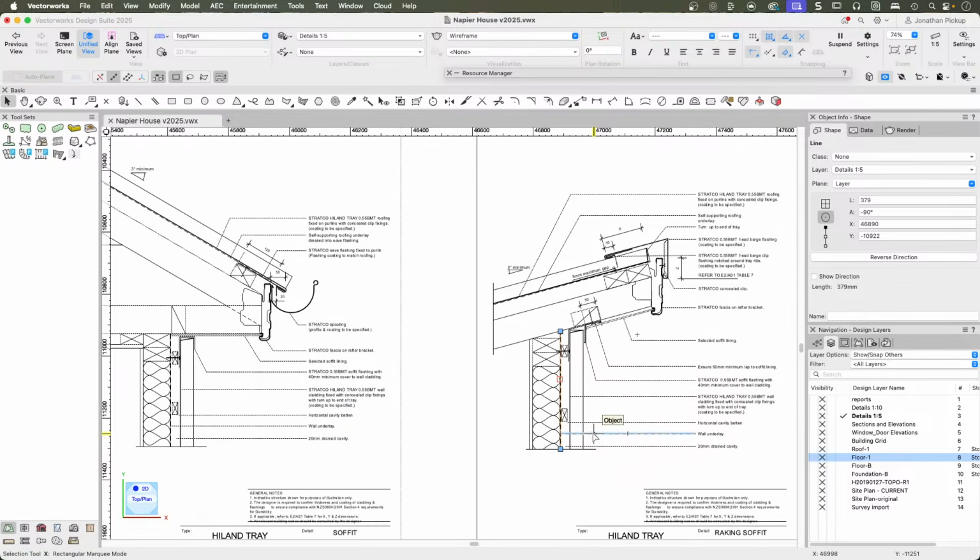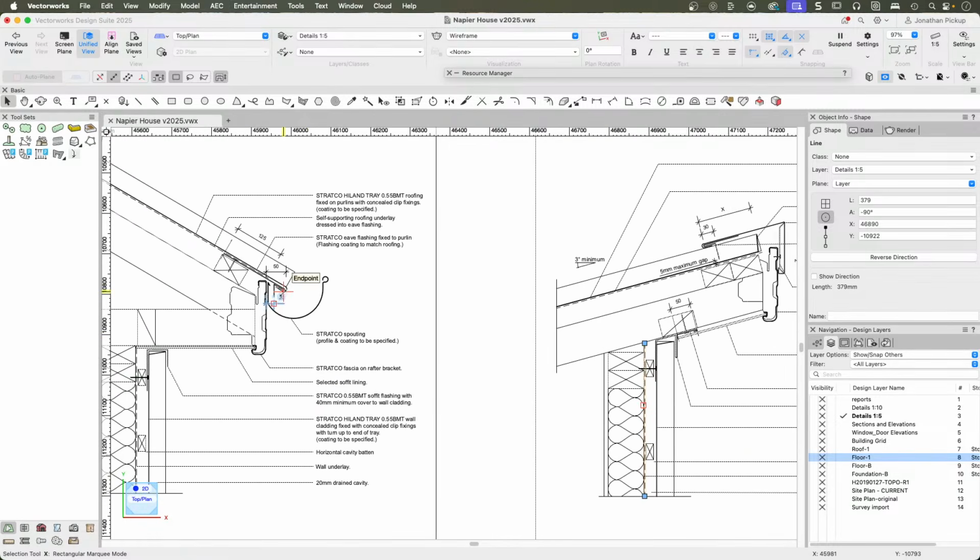So if you can't deflect the water, if you can't drain the water, if you can't dry it, then for goodness sake, make sure it's going to be durable. Where I live, if the timber is in the ground, we treat it so that it's durable. There's lots of times where you put in a timber foundation, you can't drain it, you can't dry it, you can't deflect it, but by goodness, we make sure it's durable. We treat it so that it doesn't rot in the ground. So that's one of the tricks I use, is to bring these details in.